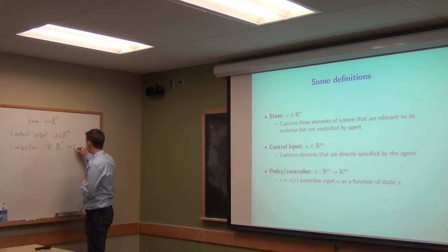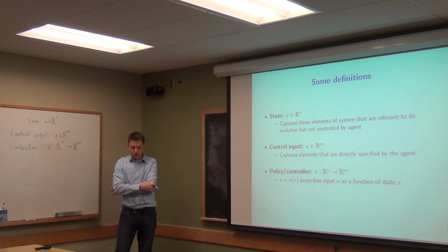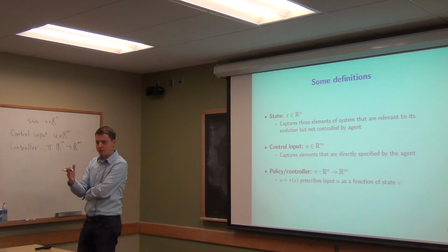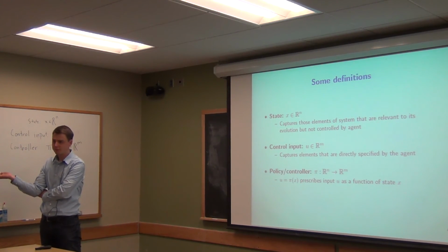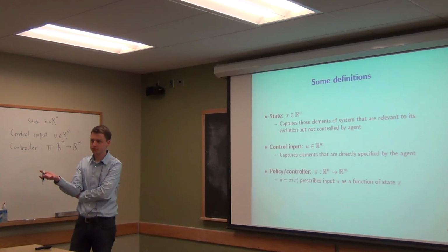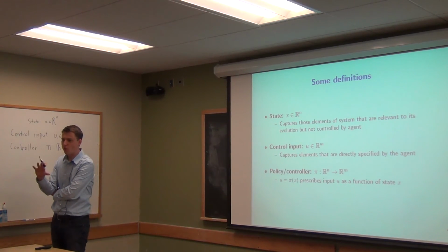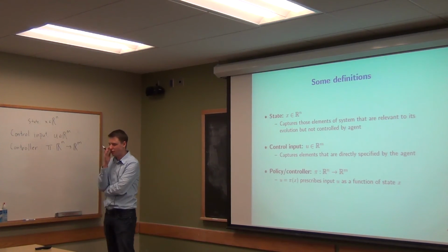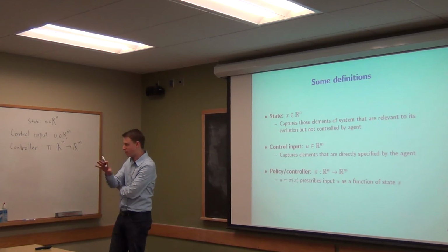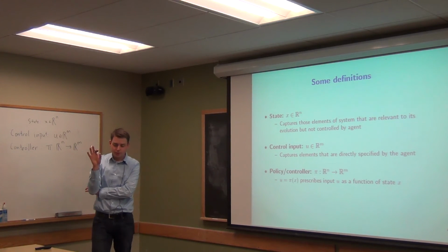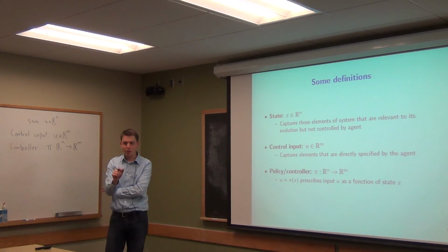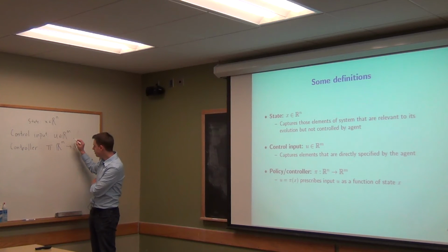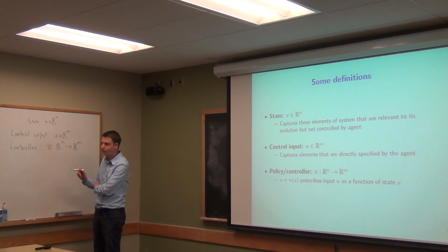to controls. So again, in our heating example, a control policy could be if the temperature is below 68 degrees, turn the heater on. And if it's above 70 degrees, turn the heater off. And otherwise, keep it what it was before. This is actually a little bit more complex of a controller because this actually depends on past states. Actually, let me revise that. That would depend on past control too. So let me have a controller that actually just says, if the temperature is less than 68, turn the heater on, otherwise turn it off. That would be a control law that prescribes control actions, whether the heater's on or off, given the state of the system.